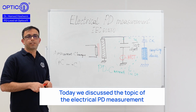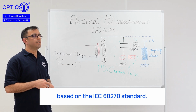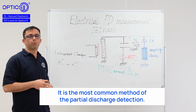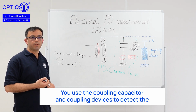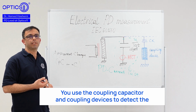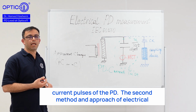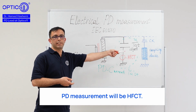Today we discuss the topic of the electrical PD measurement based on the IEC 60270 standard. It is the most common method of partial discharge detection. You use the coupling capacitor and coupling devices to detect the current pulses of the PD. The second method and approach of electrical PD measurement is HFCT.